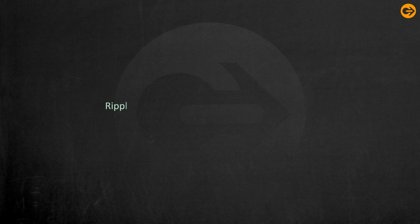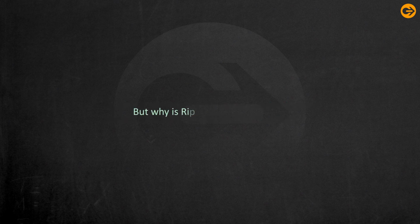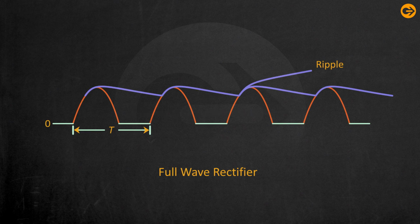Ripple factor. The ripple factor can be defined as the AC component within the DC output. But why is ripple factor required? Ripple factor is used to measure the effectiveness of a rectifier circuit. As we have discussed earlier, the ripple in the DC output of a full wave rectifier is eliminated using a filter circuit. Hence, we can come to the conclusion that the lesser the ripples, the better the performance.